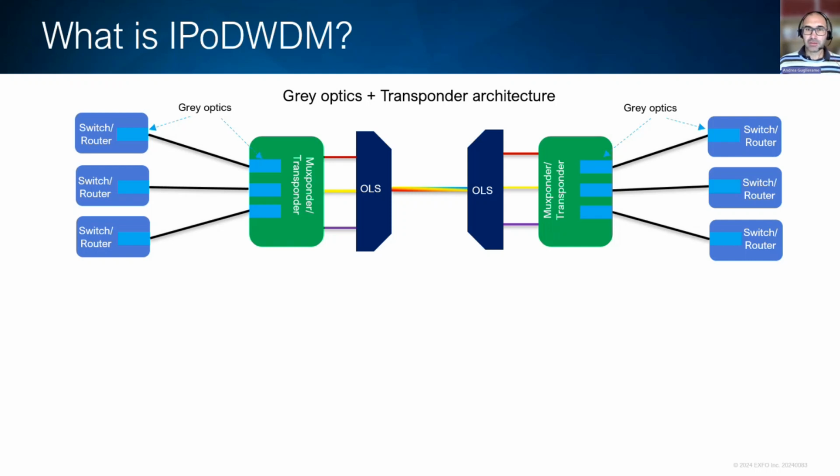Many of you probably already know, but for sure most of you already know, but let's explain what IP over DWDM is. In traditional architecture, muxponder and transponder line cards are acting as a clear demarcation point between IP and optical transport network. They are used basically to interface with the client world, and they face towards the transport section of the network, and all the optical transport functions are located in the line card itself.